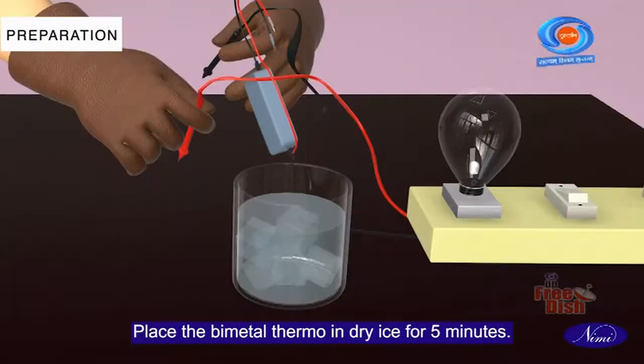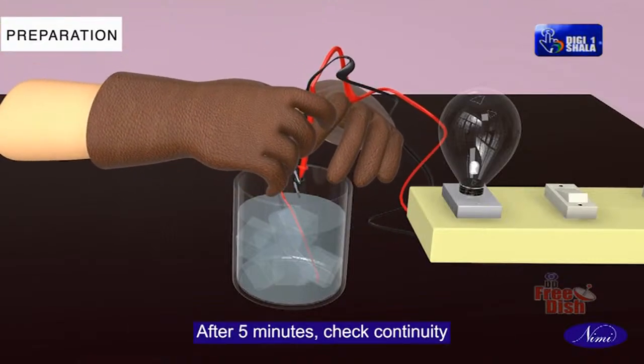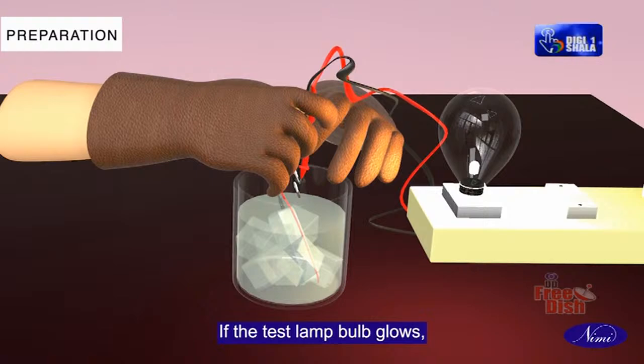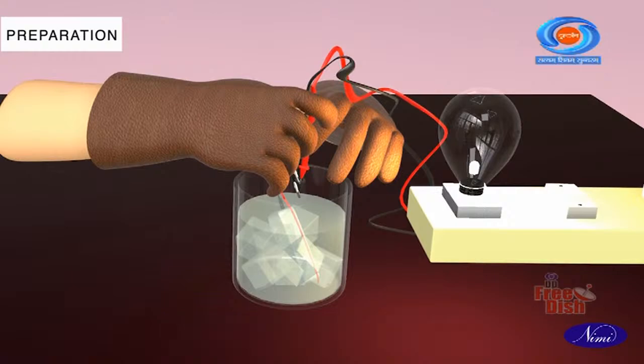Place the bimetal thermo in dry ice for 5 minutes. After 5 minutes, check continuity between points A and B. If the test lamp bulb glows, the bimetal thermo is operating properly.